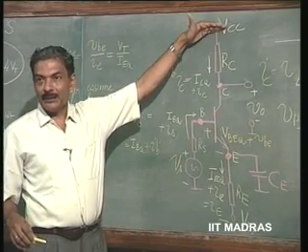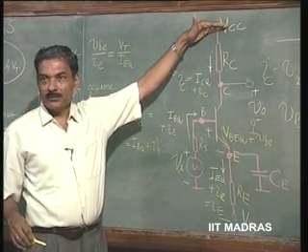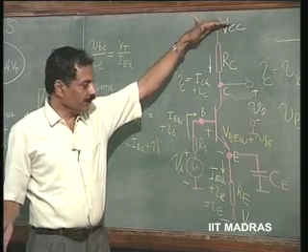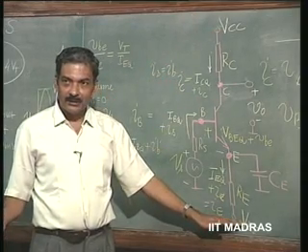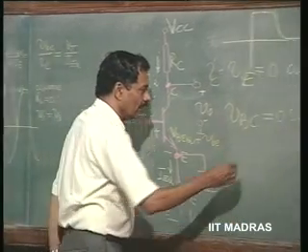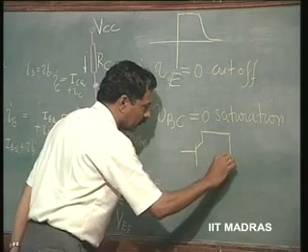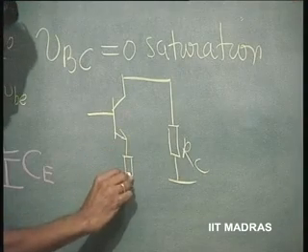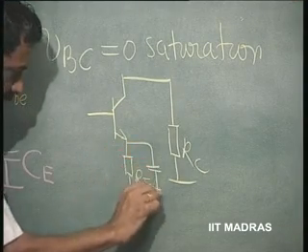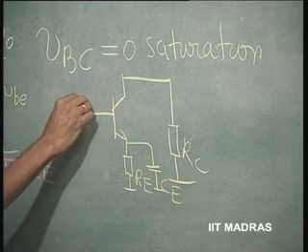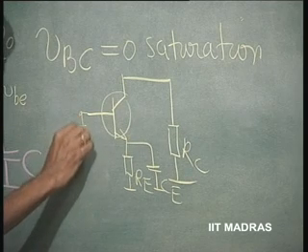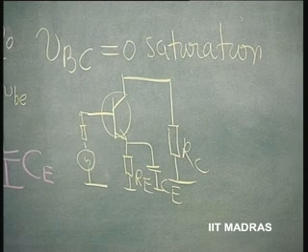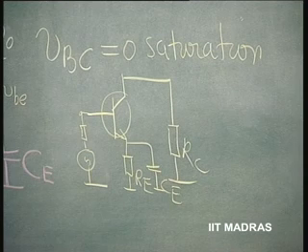For that purpose, wherever there is no change in voltage, that point is considered as a ground point. No change in voltage with respect to common ground means it is the same as the ground point. So, VCC is grounded, minus VEE is grounded. And for the equivalent circuit for only changes, RC is going to be grounded through capacitor CE, and this is the equivalent for only changes when the changes are small.